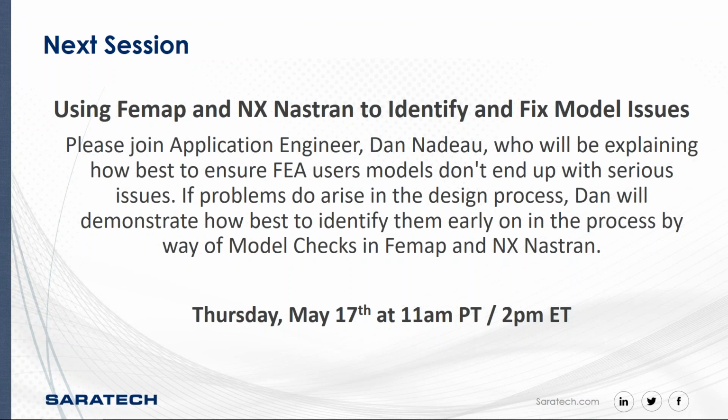That just depends on your model. Depending on the parts and how you model your mid surfaces for thin walled parts, you may include offsets or not, just to get things to line up properly. So if you have offsets, that's when you may want to change that shell offset setting for the contact.